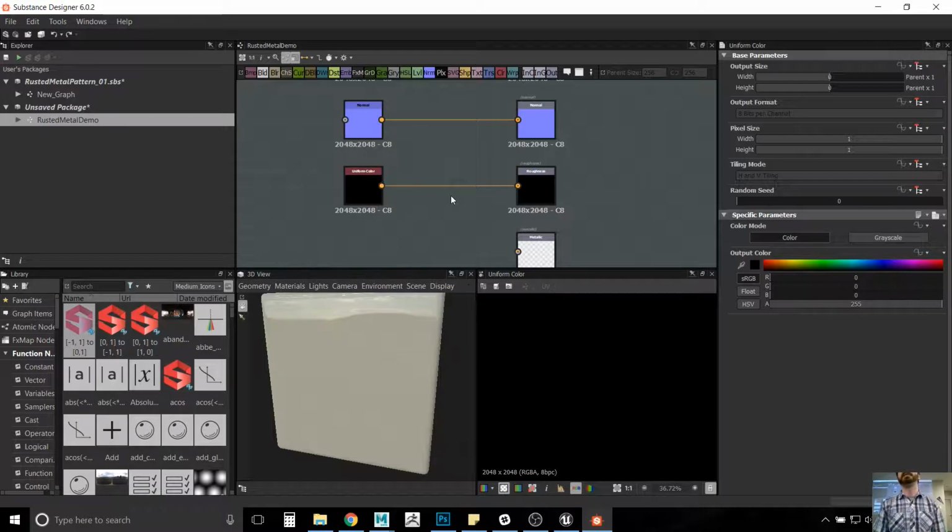if I want to make adjustments to that, what I can do is, instead of having this connected, add in a levels adjustment in between those. I want to sandwich a node in between those. So what I can do is get rid of this connection first. I'm going to hold down Control, or actually, no, I apologize. Control's used in Unreal. You just select the node, highlight the node, and then delete that string in between to delete a connection.